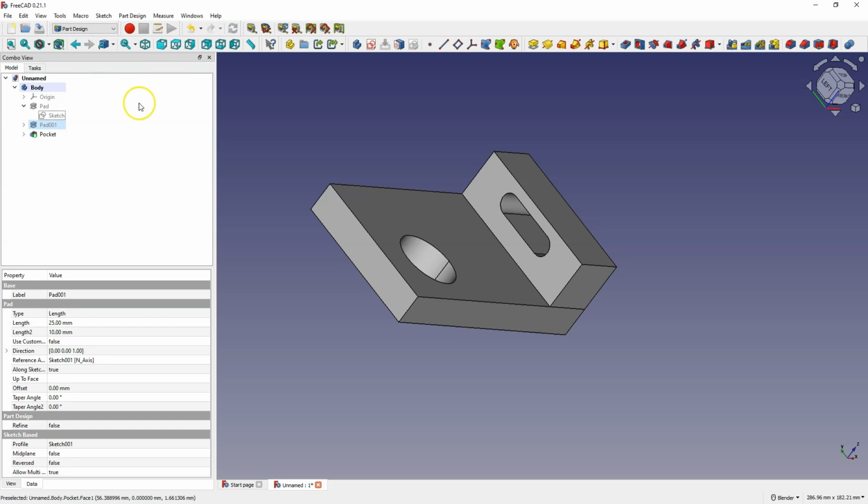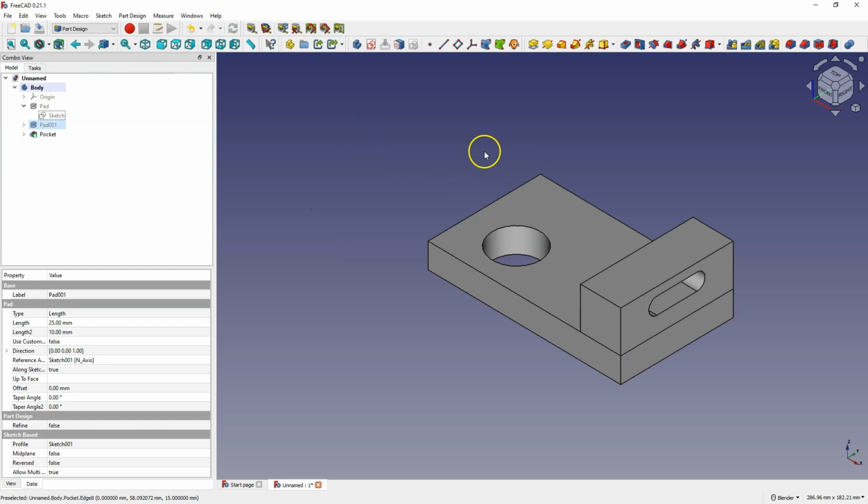And, okay, we use two basic operations to create 3D solids. One operation is the extrude operation, which adds material based on the 2D sketch, and the other is the pocket operation, which removes material based on the 2D sketch. We have two more basic operations for editing 3D solids, and they are the operations fillet and chamfer. Fillet operation allows you to add rounded edges.